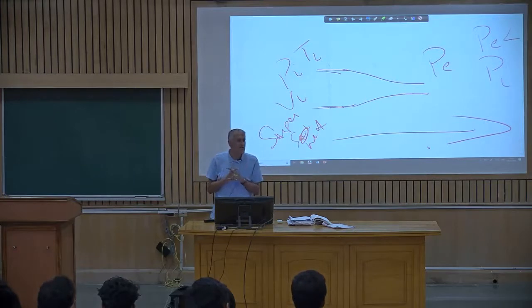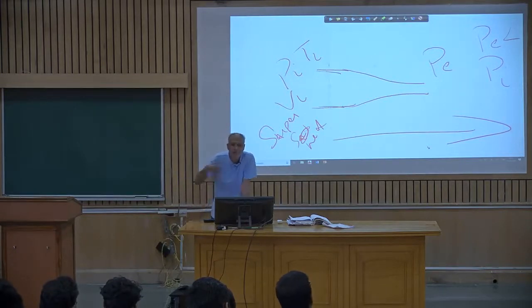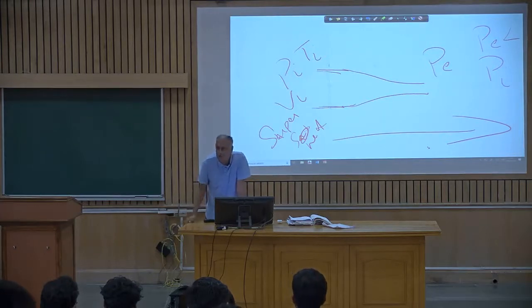Did the driving force increase or decrease? It's already coming with a pressure. If you put a restriction, pressure also goes up. So what happens to delta P? Decreases. The pressure gradient decreases. So what does the plumber usually say? Pressure kam ho gaya. When there is clogging, he says pressure kam ho gaya. Got it? What he means is the pressure gradient went down.